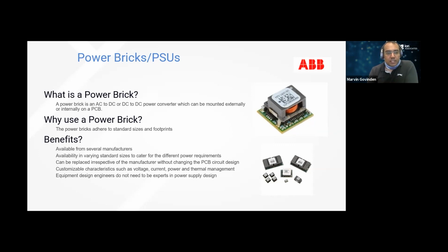What is the advantage of having a brick? They're available from many manufacturers. They conform to a standard made by DOSA. I can think of that as an agency that has standardized how these bricks should work, what types of voltages they should have, what the thermal performance is, and many characteristics, and they're all certified.